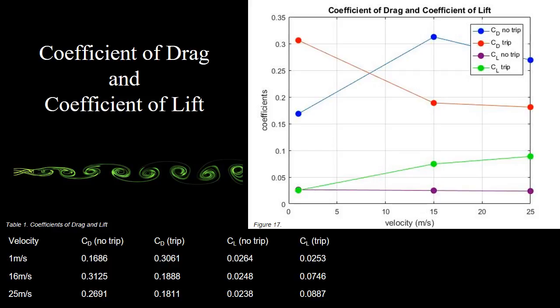The slight errors making the lift coefficients not 0 could be due to the inconsistencies in the free stream flow and the cylinder not being accurately lined up with the stagnation point, pointing directly into the flow.